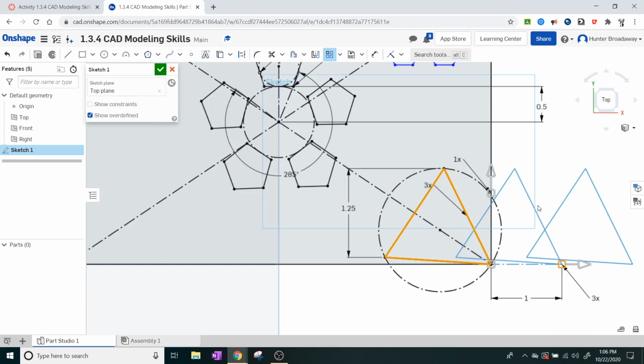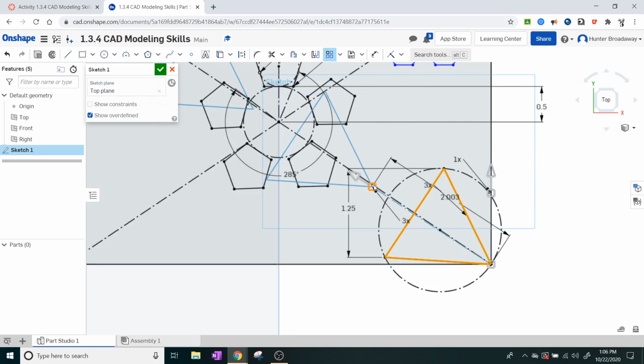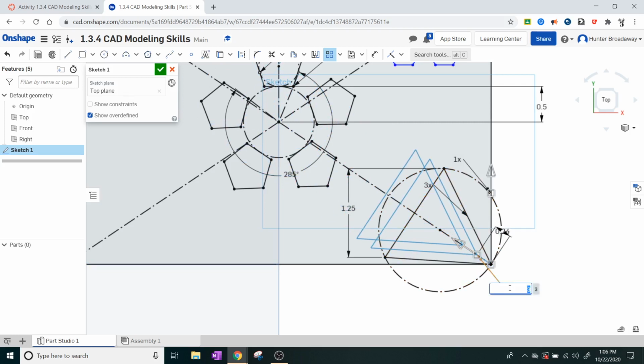I'm going to click on that white box down here and drag it in place along the construction line, and get it going right about there. I'm going to click on the arrow above it to shrink them down. See the 3x that's moving along with it? That's the 3x that I'm going to actually need to grab. So I'm going to click on this and make that 5, and that's going to create 5 more triangles. Oh yes, that looks much, much better than what I just did.